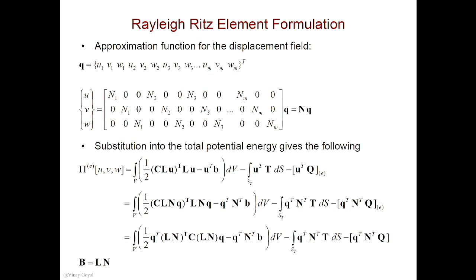Also for cube elements, here are... For what? For a cube. Yes. So there are 8. So m in this example will be 8. For the cube, it will be m equals 8. For a tetrahedron, m will be 4. For a second order tetrahedron, which will be 10 nodes, m equals 10.